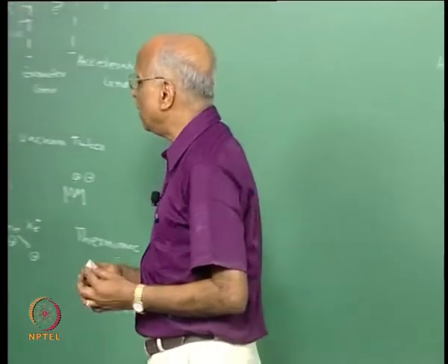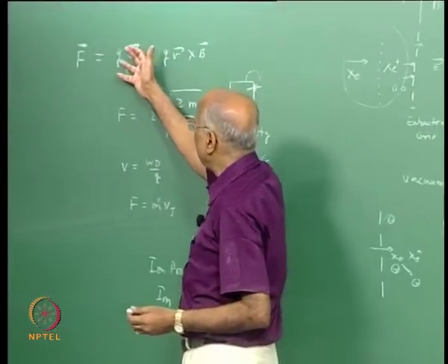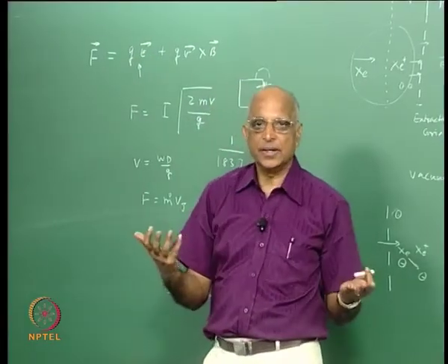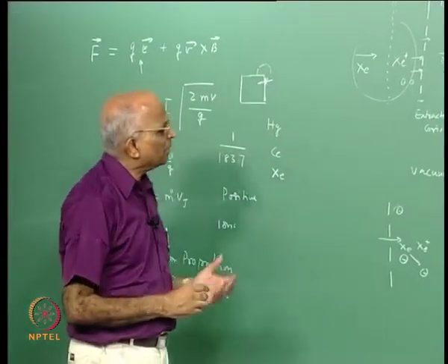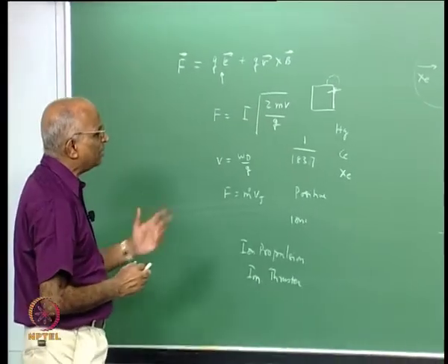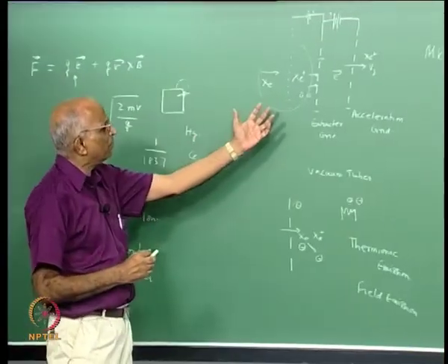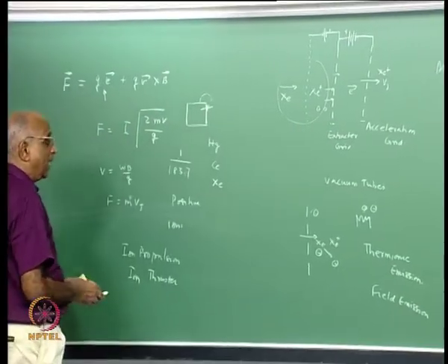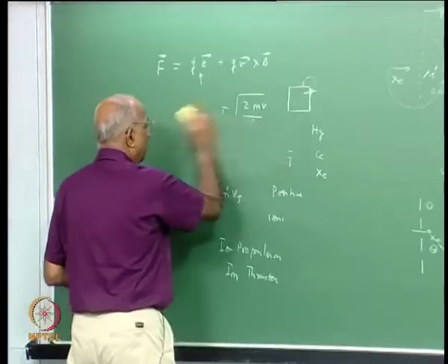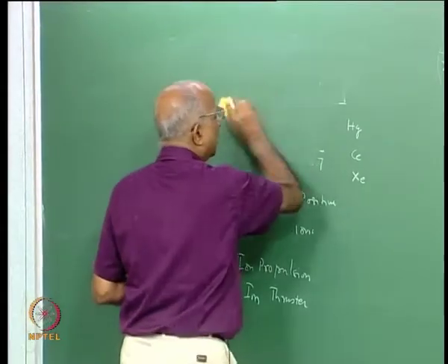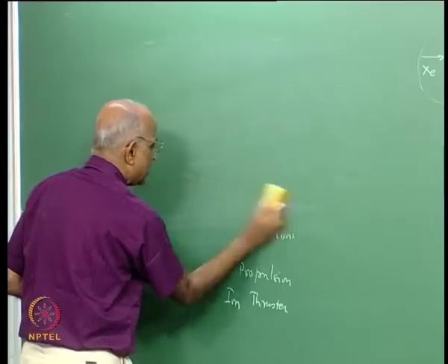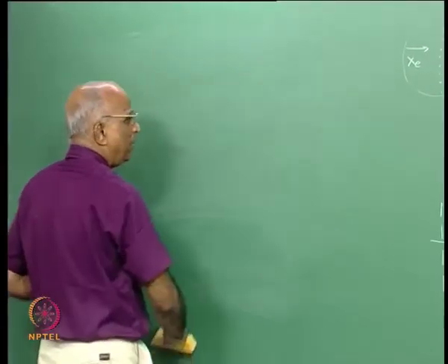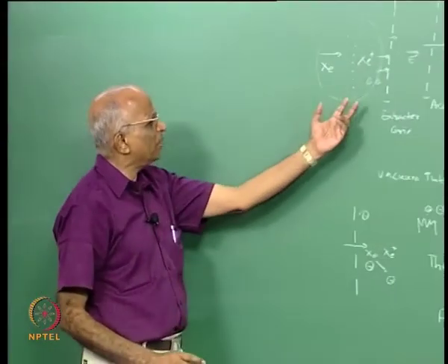Using the electrical field as it were, if I can generate charge in a particulate, I can accelerate it and I can get a particular thrust. Well, this is all about electrostatic, but having studied it, let us see, are there any specific problems in this? Is it something which is so readily usable, and are there some improvements in it? Because we do not see ion propulsion being used as much as some other forms of electrical propulsion, and the reason being, let's see what the problems are.